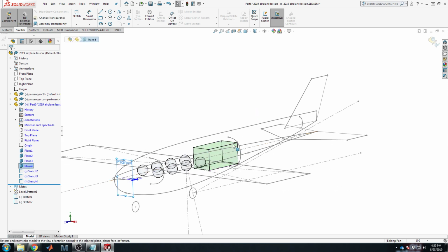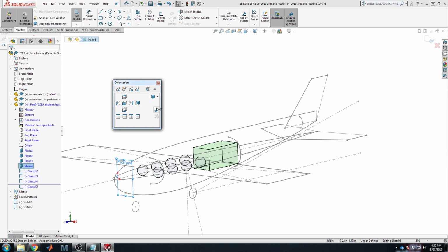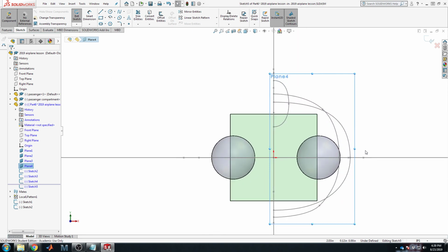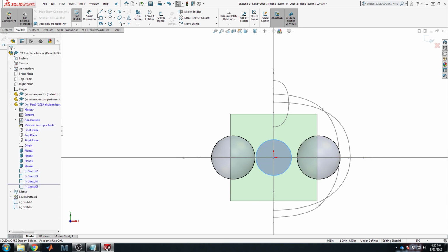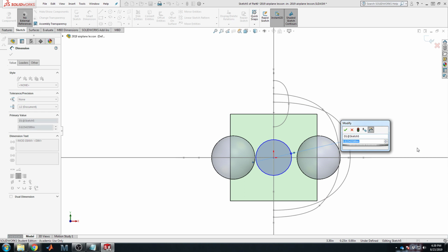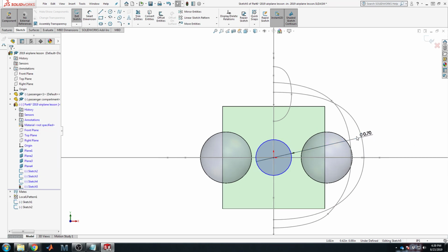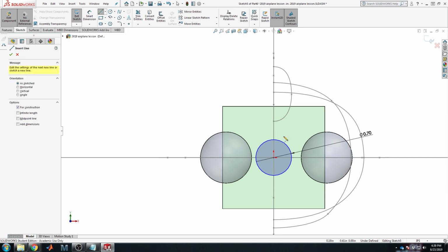Right. Do the last one, the front one. Save. Gosh, save this stuff all the time. So in the front element, do a sketch. And in this case, I'm just going to do actually half circle. I do want it to be almost a perfect circle. Nope. There. Let's go with a size of, I don't know, 0.7 inches. Something small-ish. And that'll let us have this nice, perfectly radial nose.